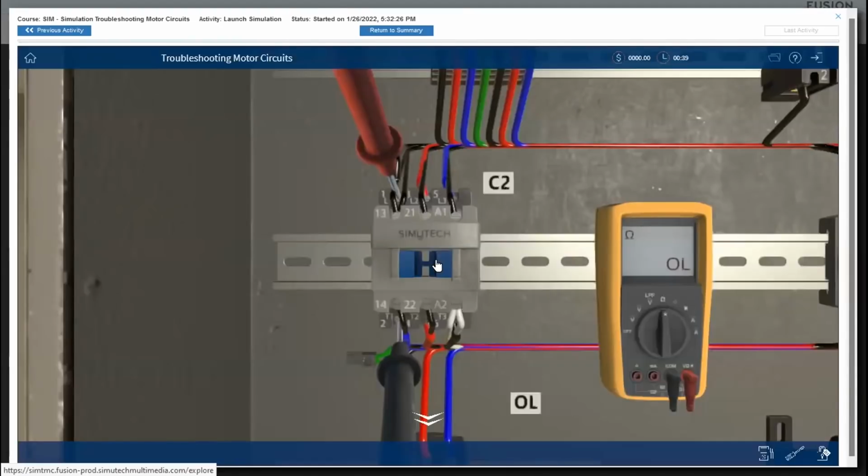Well, the problem is, think about it like this. What if the motor was shorted out, right? If the motor had shorted windings and you push this in, well, what you're creating is a phase-to-phase short circuit. You're bucking phases. Most of us are dealing with 480. 480 phase-to-phase, there's going to be an arc. And where's that going to happen? Right here where we are. So remember that one, please.